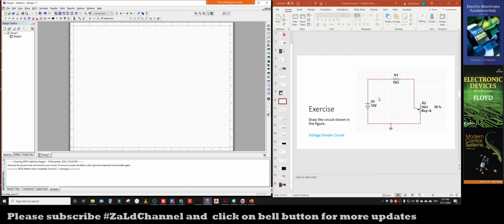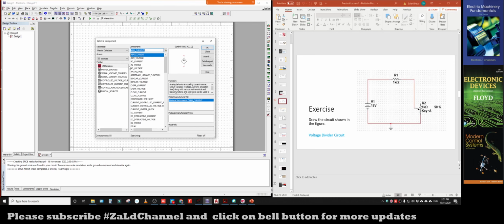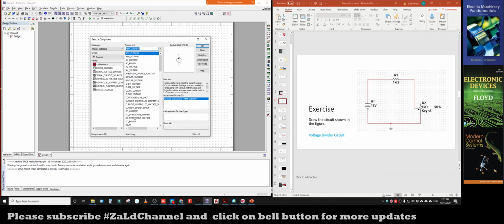So we will start with placing this component, which is battery. All right, so I'm going to put this battery component. Just make sure that you click any button is fine, but we have the place source here. You can just click on place source. Okay, so the library will appear like this. Now we are going to place source, which is the DC source. Okay, so we will find the DC source.